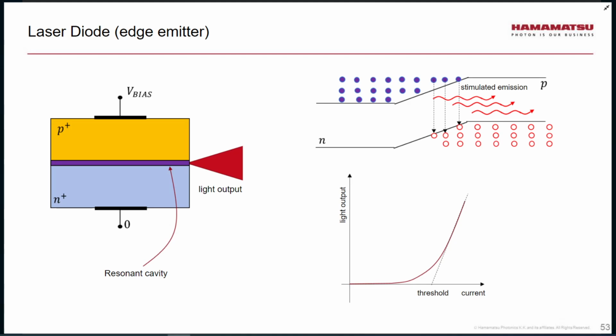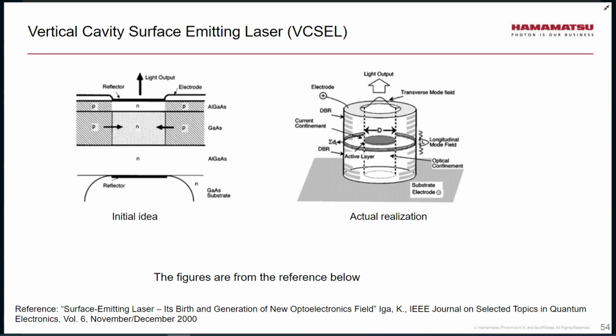However, light from a laser can have a large degree of coherence, temporal coherence, and spatial coherence, and that will depend, again, on how many modes the laser produces. If I have a single mode, a single wavelength, then the temporal coherence is going to be very large, even hundreds of kilometers. Such lasers are of great interest in another type of automotive LiDAR, the FMCW LiDAR.